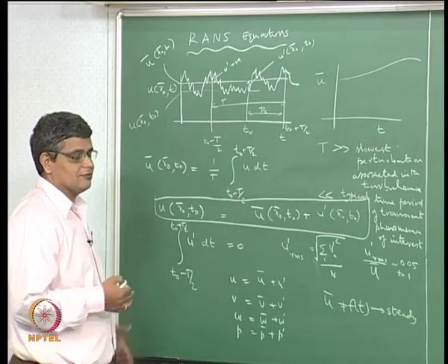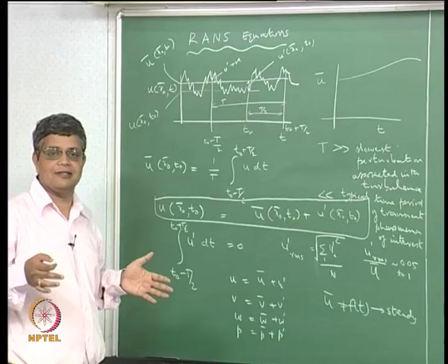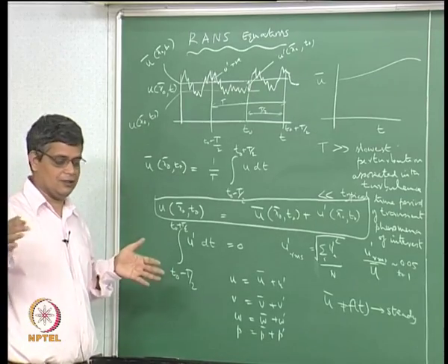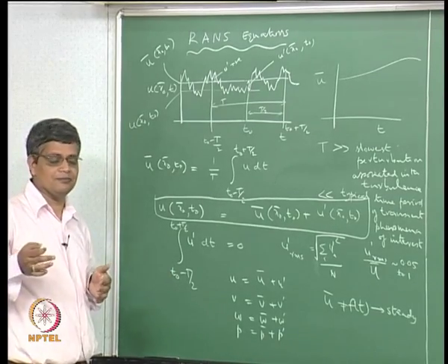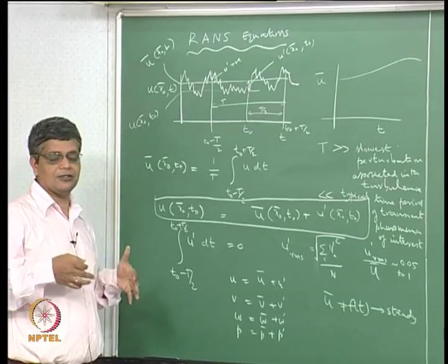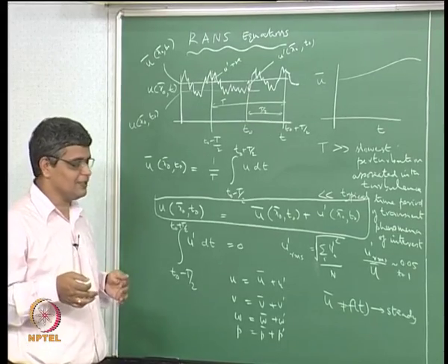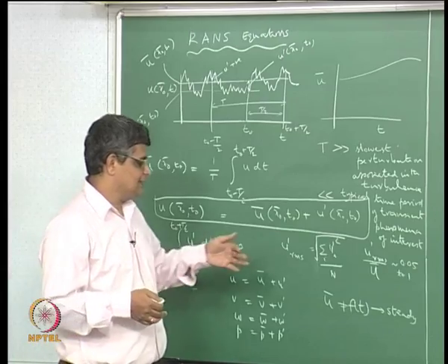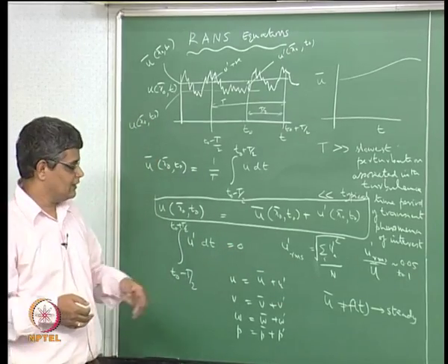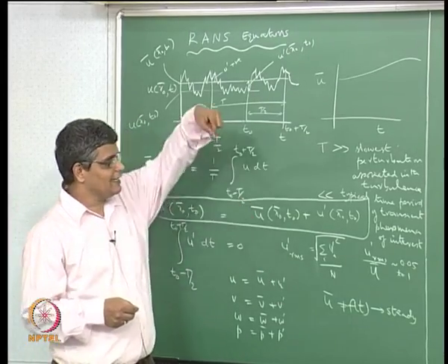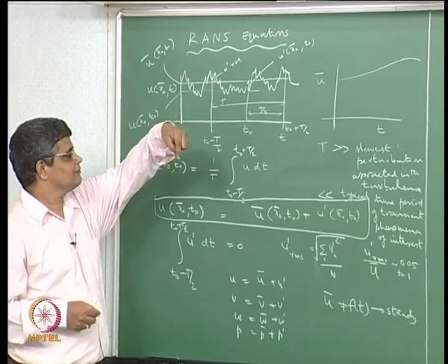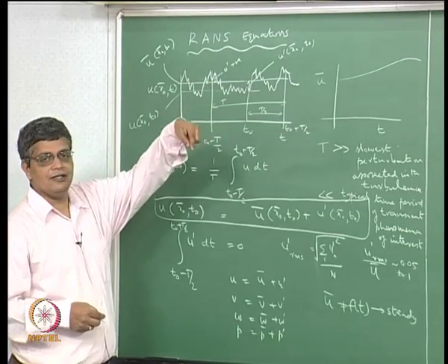And if you have maintained a constant pressure gradient across a straight pipe of a given diameter, and if the Reynolds number is of the order of 50,000, then we can expect the pipe to reach a steady flow condition where the time average velocity at a particular radial location will not vary with time.